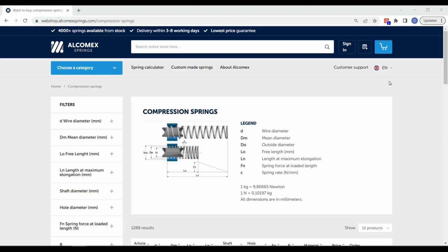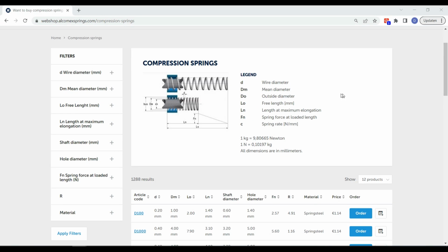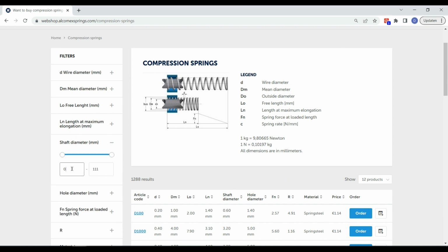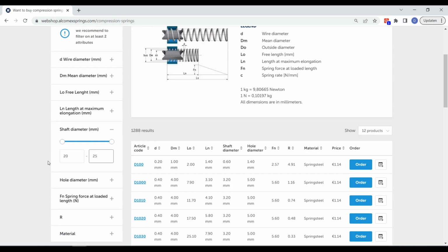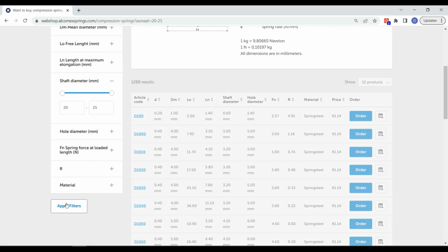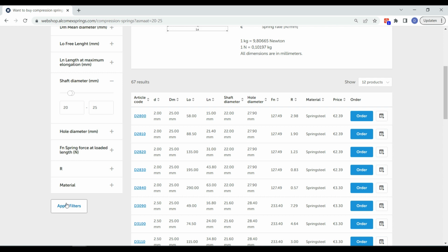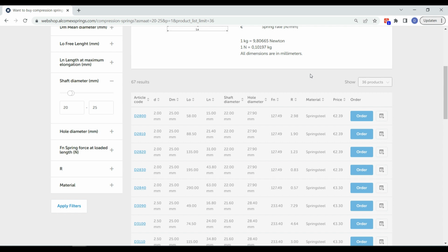Now it is time to select a spring so we can fill in the spring constant and check what the value for net force is and whether the spring has the minimum required deflection. We can also play around with the groove angle and the spring preload to achieve the desired net force. There are several combinations possible, but I wanted to limit the spring force to about 500 Newton for safety reasons, and I also wanted to keep the spring length to a minimum.